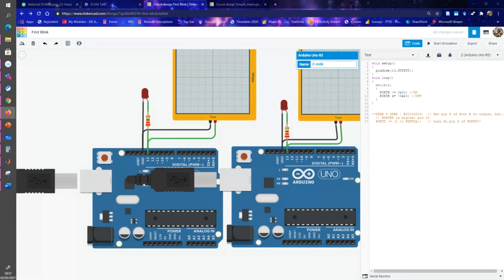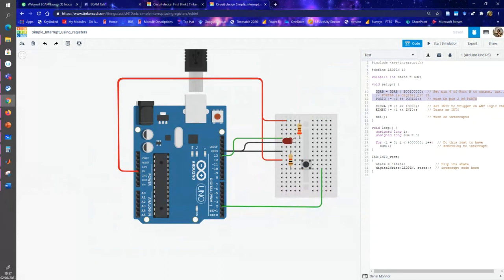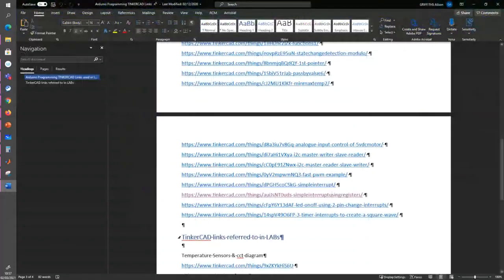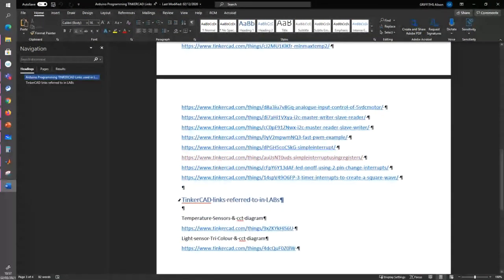So this is the data direction register for port B. So port B, and then rather than 0x, it's binary, so we just say capital B. I was asked a question about hexadecimals before, and I don't have any hexadecimals in that one. However, I'll probably have some hexadecimals in some others. These are what you're going to be doing later on, by the way.